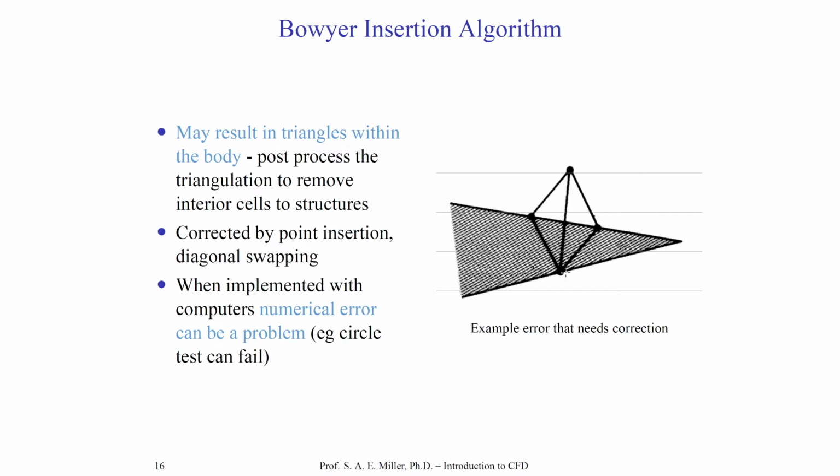It has satisfied all our tests of the algorithm, and so many logical statements must be placed within these algorithms to do checks to make sure that the connectivity is not violating the surfaces of vehicles, for example, especially where there are angles like at the end of a trailing edge of an airfoil. This can also happen in other locations or any regions where the part might be thin, for example, at the end of a nozzle lip. The Watson algorithm itself rejects elements, triangles in 2 dimensions for instance, from the set of all the triangles with non-empty circumdiscs. These can either be removed from the mesh or replaced with ones that pass the test.